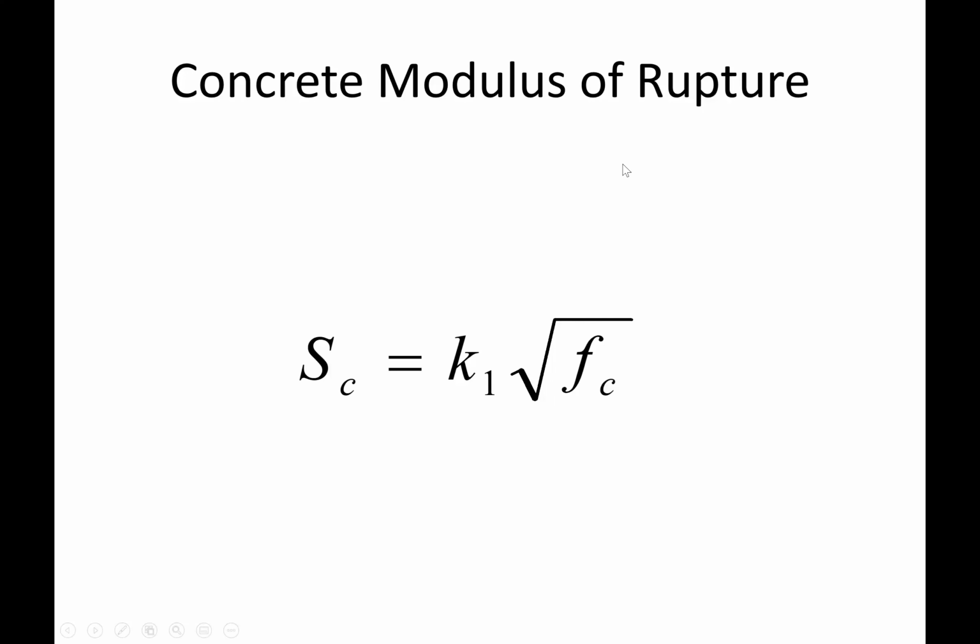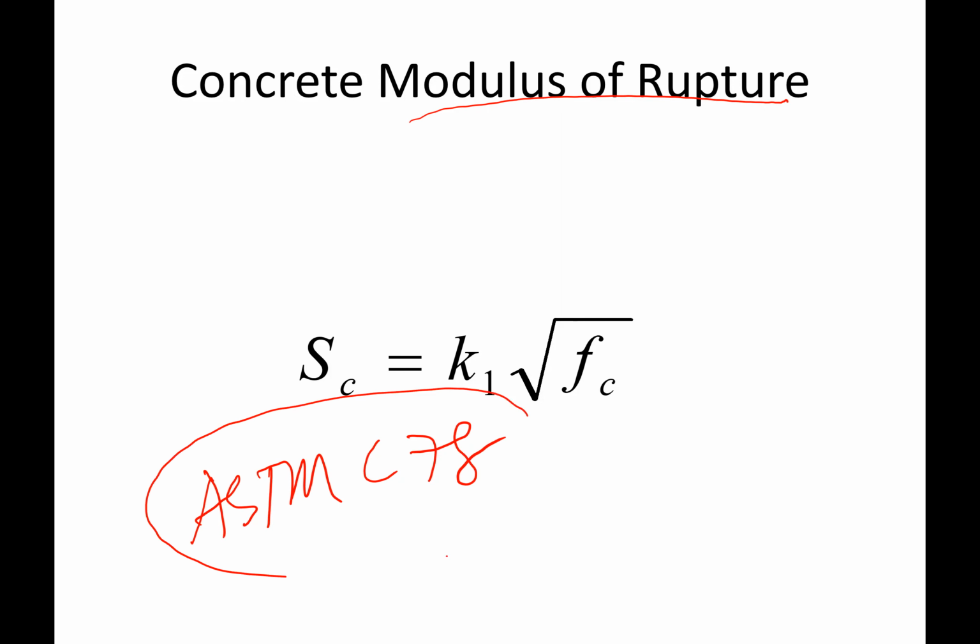All right. Another parameter that you need to know is the concrete modulus of rupture. Okay, concrete modulus of rupture ni awak boleh buat, you're using also a lab test according to ASTM C78. Okay, it is a mean value, determined after 28 days using the third point loading. Okay, this is the testing that you need to conduct first in order to determine the modulus of rupture of